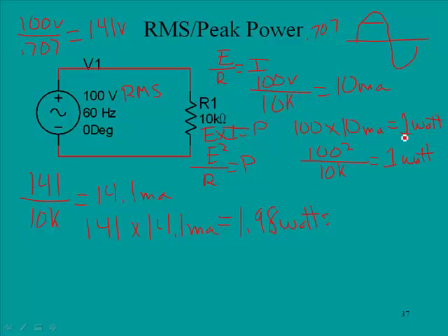Say let's amplify it out 100 times, and so here you've got a 100 watt amplifier rated in RMS, and then there's another amplifier that says it's 198 watts, but this is in peak, and technically if you do the math, they're the same power. So anyway, this is a discussion related to RMS versus peak power.